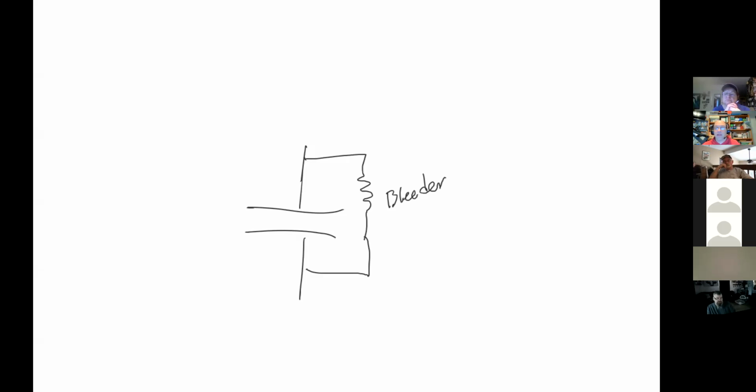Yeah, if you've unplugged the power supply for your laptop, and it has a little LED on it, notice that the light fades gradually. That's actually the capacitor inside bleeding off through a bleeder resistor, which is why it doesn't just turn off immediately, depending on whether it's hooked to the computer or not.